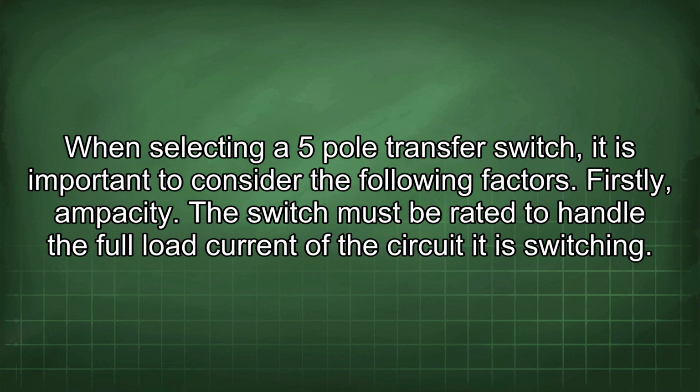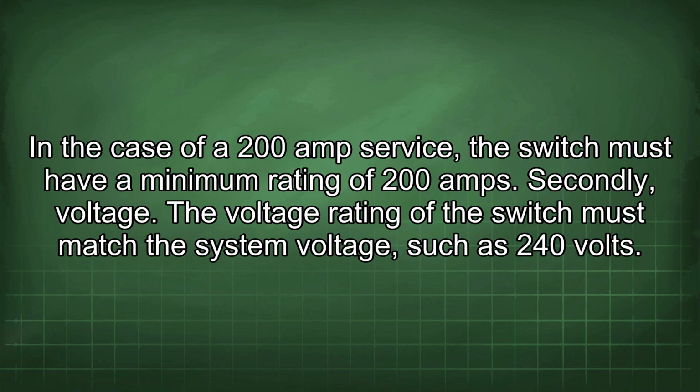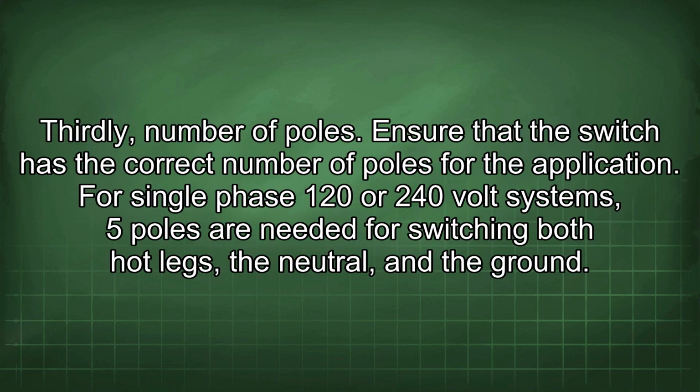Firstly, ampacity. The switch must be rated to handle the full load current of the circuit it is switching. In the case of a 200 amp service, the switch must have a minimum rating of 200 amps. Secondly, voltage. The voltage rating of the switch must match the system voltage, such as 240 volts. Thirdly, number of poles. Ensure that the switch has the correct number of poles for the application.